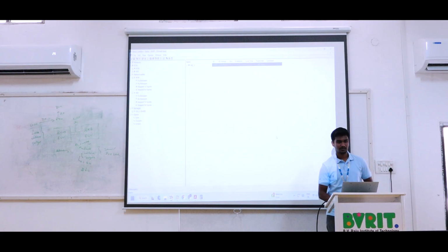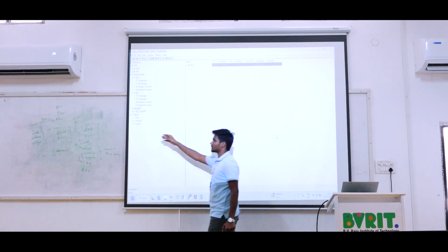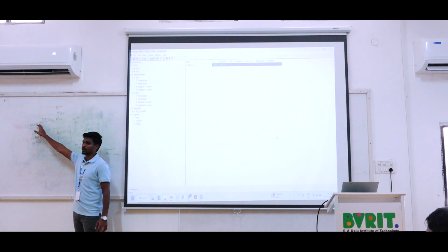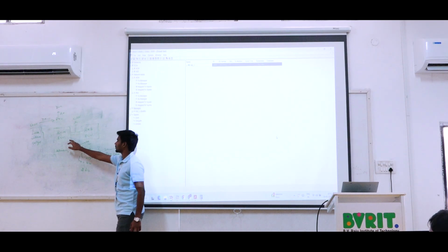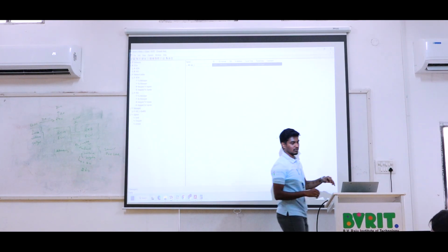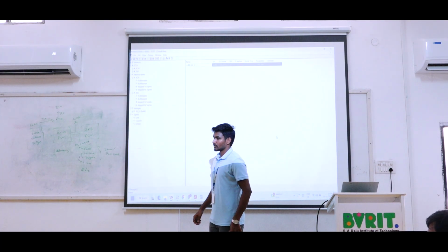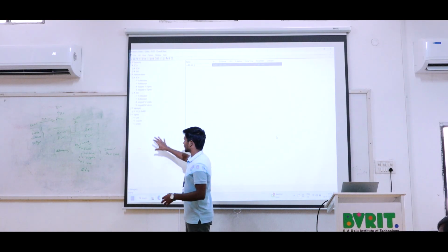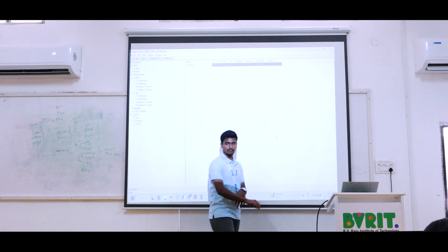Okay. So as of now, we have created the signal values, and we have mapped this ID as ID number 400. Now we are going to set the TX concept and then the RX concept. We are going to map it for RPA and then BCM. We have created a signal. Now we kept only RPA messages. BCM messages we are not creating, because the BCM is going to just receive the value. It is only to transfer the data.